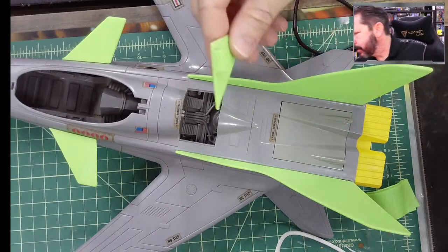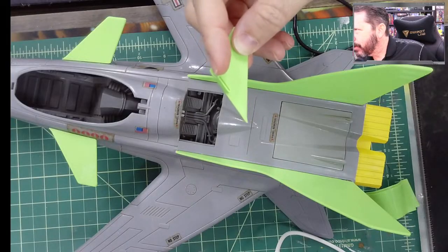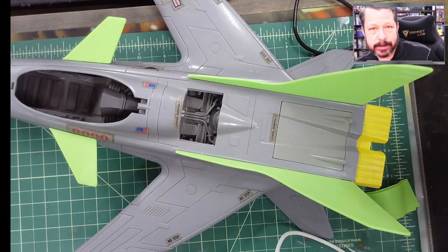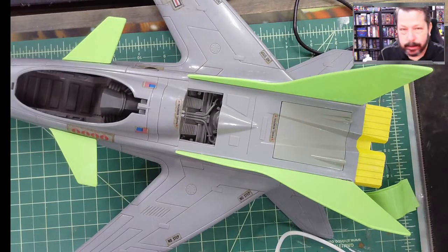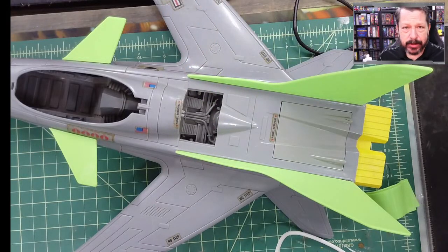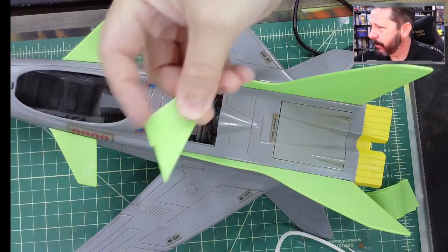These were not terribly long prints, but if you do have something, just print the one little piece that has to interface. You know, print 10 layers of that piece, or isolate it somehow so that you're not printing the whole thing over and over again. You can isolate it just in the slicer. You don't have to go model it separately. You can just, let's say that I wanted to print just these little interface pieces.